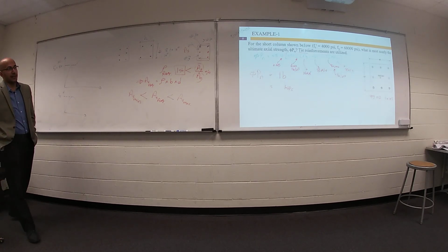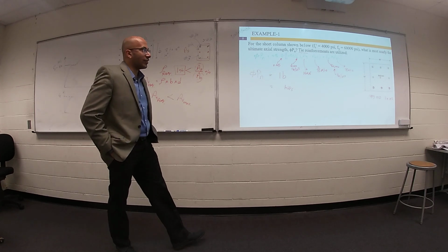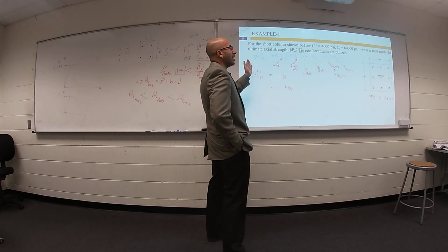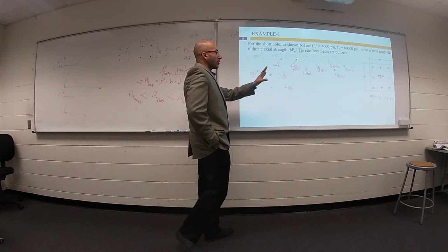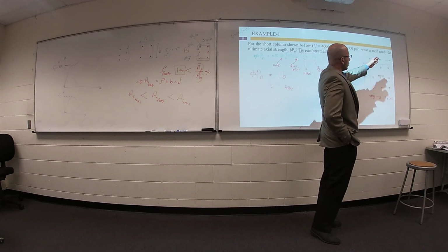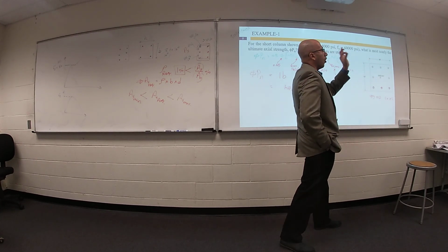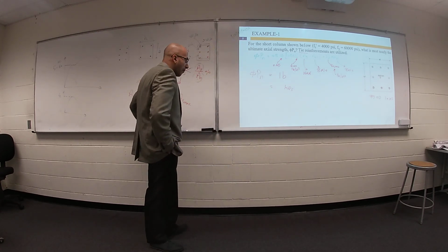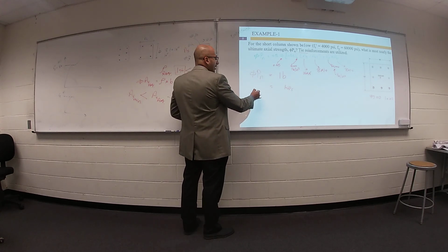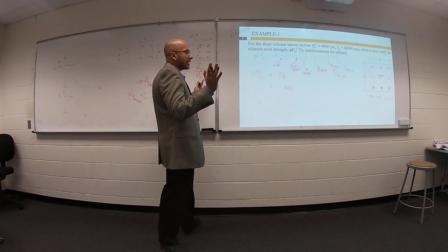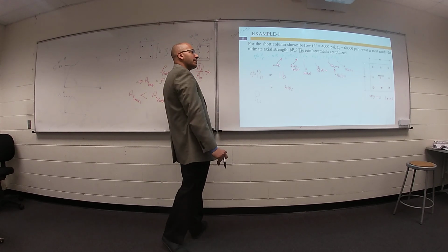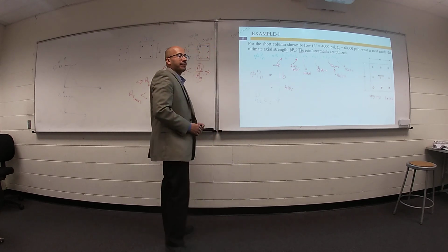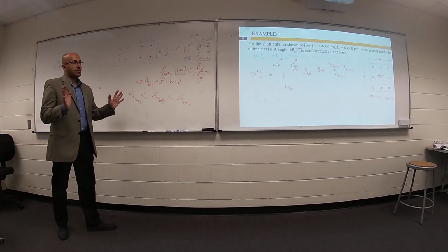This example is very simple because everything is given. Your column dimension is given, your steel reinforcement is given. You are just using the equation for design. So this column with these dimensions and this steel reinforcement can only support this force. If you would like to make some design, your reaction from structural analysis or from RISA on this column must be smaller than or equal to this design number. This is our design philosophy.